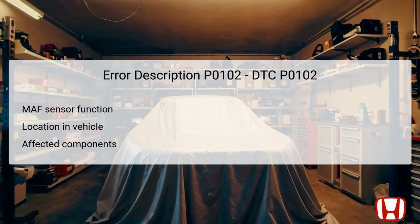The mass airflow MAF sensor is located between the air filter and the throttle body of the vehicle. Its primary function is to measure the volume of air entering the engine to maintain an optimal air-fuel mixture, which enhances combustion efficiency. A low voltage reading from the sensor indicates that it may not be functioning correctly, leading to issues such as poor engine performance, increased emissions, and potentially stalling.